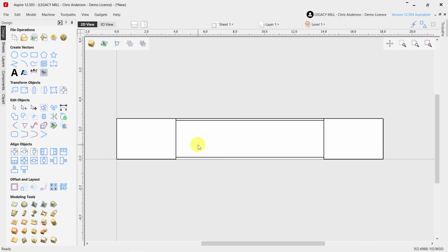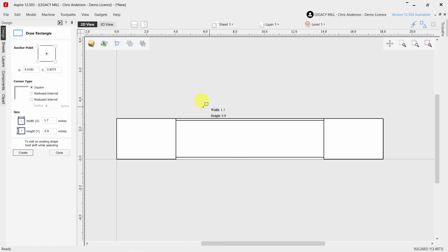From a top view or side view, this represents a square section on the ends and a turning round section in the middle. So let's help visualize what the cutter is going to do to a square blank to get to this finished turned round diameter section. We're going to quickly draw a cutter here. I'm going to draw a rectangle that represents the type of cutter we're going to be using throughout the sequence, known as a flat surfacing cutter. And let's give it a shank while we're at it.